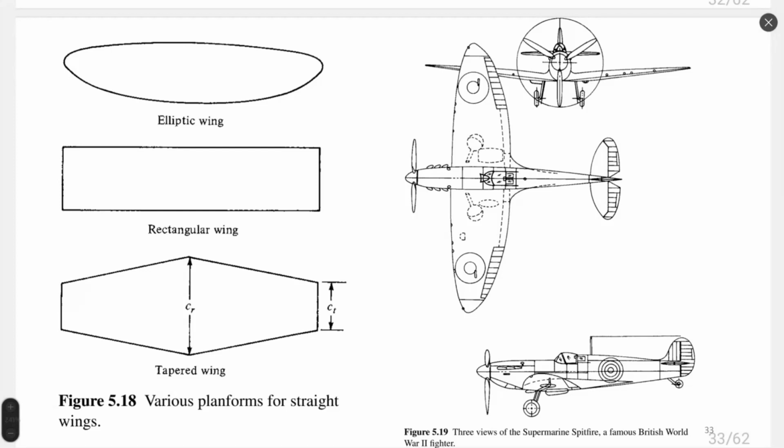Rectangular wing by itself is not the best solution nowadays because a rectangular wing has the biggest value of induced drag and losses associated with induced drag. Rectangular wing has a problem with the maximum flight velocity, so it can be used for low velocity applications.